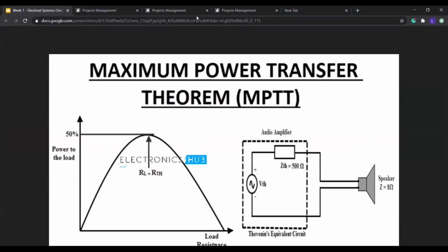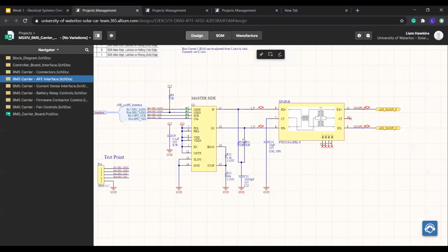So going back to the schematics, you can see that there's two 62 ohm resistors in series, which is 120, well, it's 124 ohms, but it's usually better to over terminate the line than under terminate it. So also shown by this diagram here, you can have just one resistor, or you can have this called split termination. And this is just a method to help, again, reduce common mode noise.